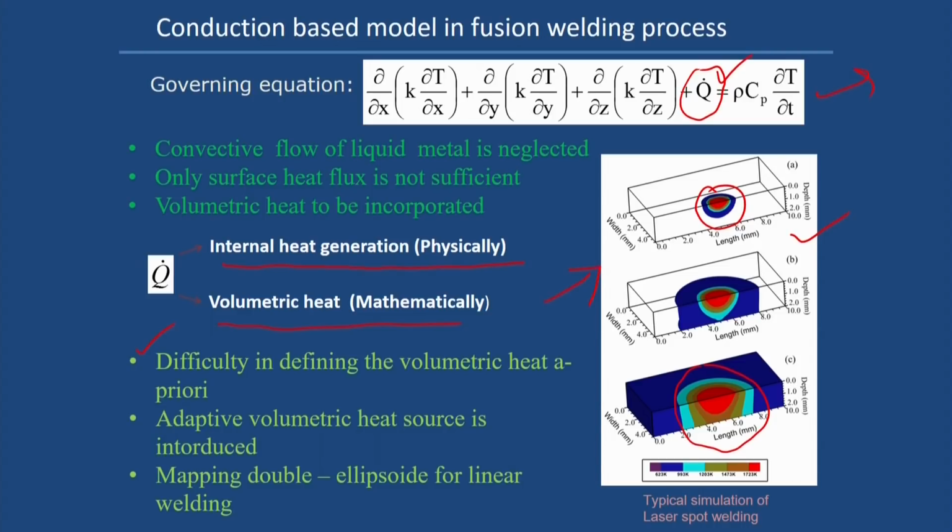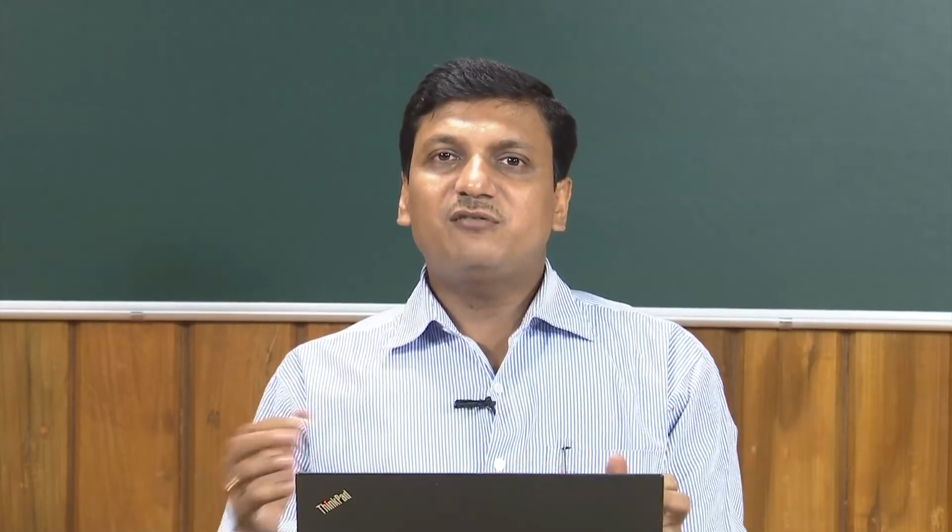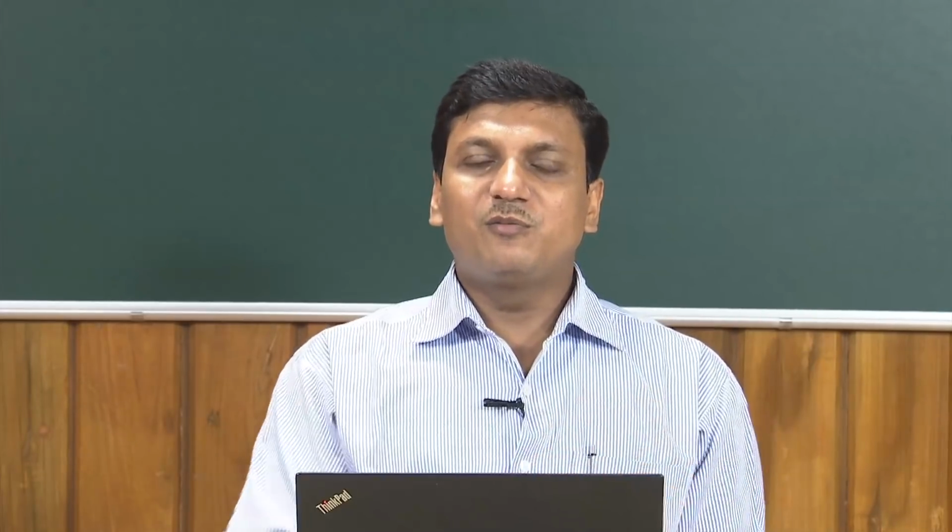That means it is very difficult to define the volumetric heat source before the start of the simulation. So, in most cases, the heat source term is defined by looking at the experimental values, the experimentally measured length and width, and based on that we can map these to the volumetric heat source term. So, that is one way, and another way is if we incorporate this volumetric heat source term